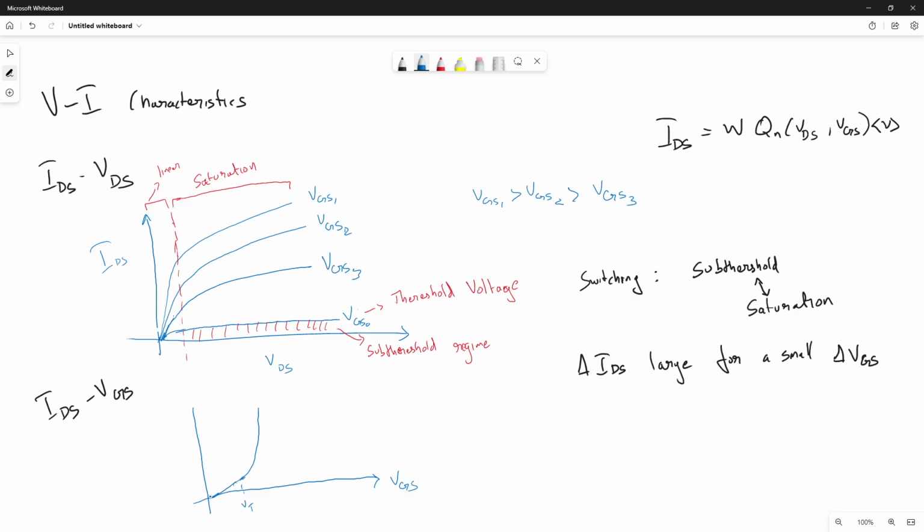Actually, it shouldn't. I mean, the threshold voltage is based on the metal oxide semiconductor regime. VDS has no influence on that. Essentially, increasing VDS will only give me a higher current. That is all. So I have VDS 1, sir, and VDS 2. Again, from our old barrier reasoning only. And this is VDS 1. Increasing VDS will increase IDS.